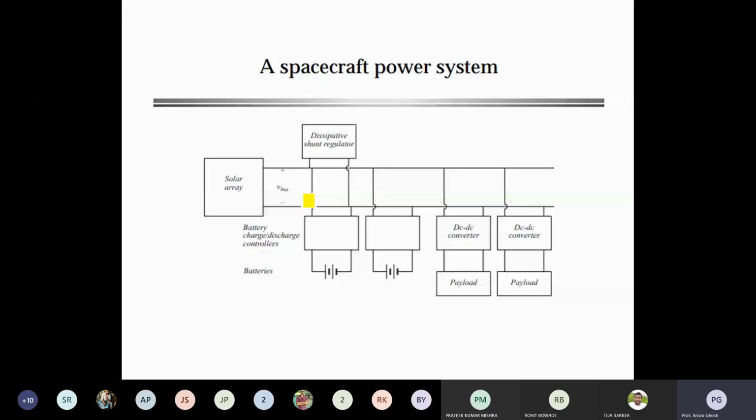If the renewables are there, you are not able to directly integrate them to the internal grid of that spacecraft, because it is an independent source of power, having independent sources of power. So there are definitely some different grids, and a single grid will be there. The solar array you connect directly to a DC-DC converter, because the output of the solar array is DC. So it will be regulated, directly DC-DC from your solar panel to your DC grid.